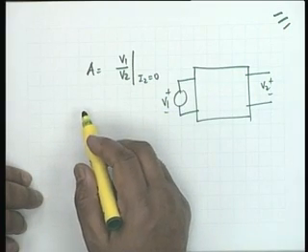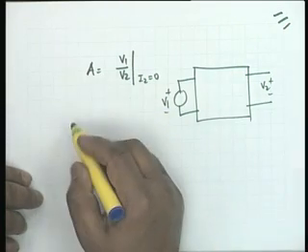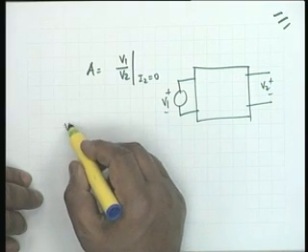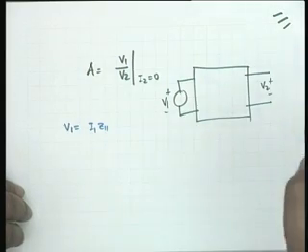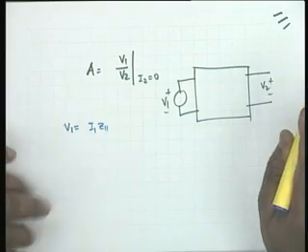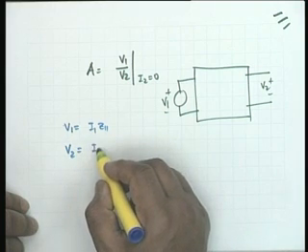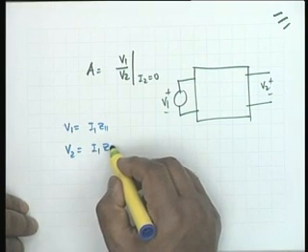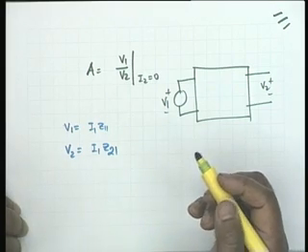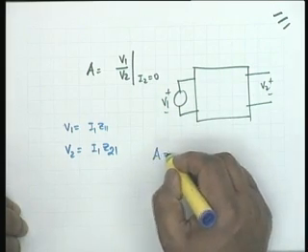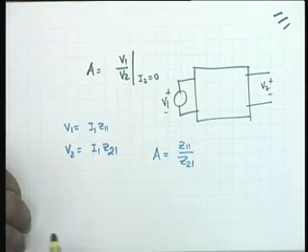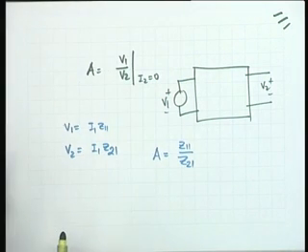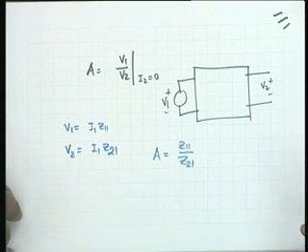Now, please do follow me. If you recall, our Z parameter definition is V1 equal to I1 Z11 plus I2 Z12. I2 is 0, so let me not write that. The other is V2 equal to I1 Z21. Agreed? Therefore, my capital A shall be simply equal to Z11 by Z21. Is that clear? So, if you know the Z parameters, I know the capital A parameter, the transmission parameter. It is simply the ratio of Z11 to Z21.